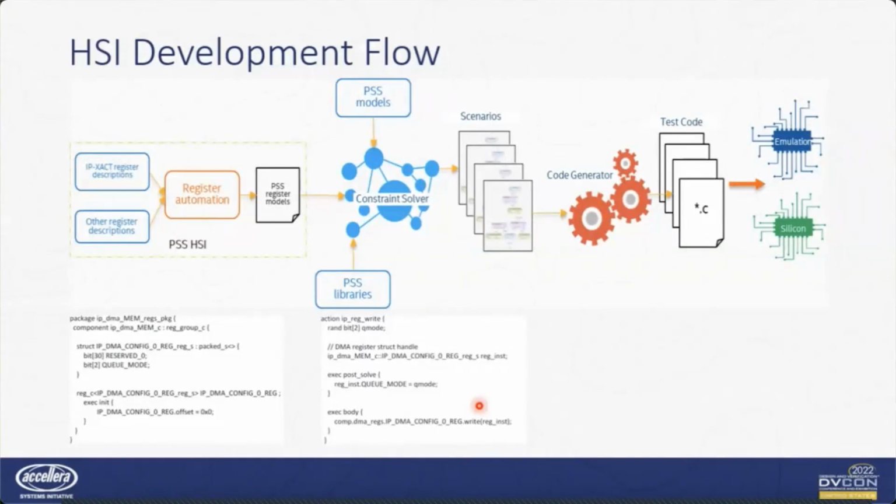And finally, HSI is not just about writing a register. You can write an interrupt handler. You can poll on a condition. You can add synchronization points between, let's say, concurrently running driver code. You can combine it with PSS memory allocation to, let's say, write the address handle of a descriptor into an IP register. So you have things like for each, you have repeat, you have if statements which can be used to, let's say, generate conditional code.